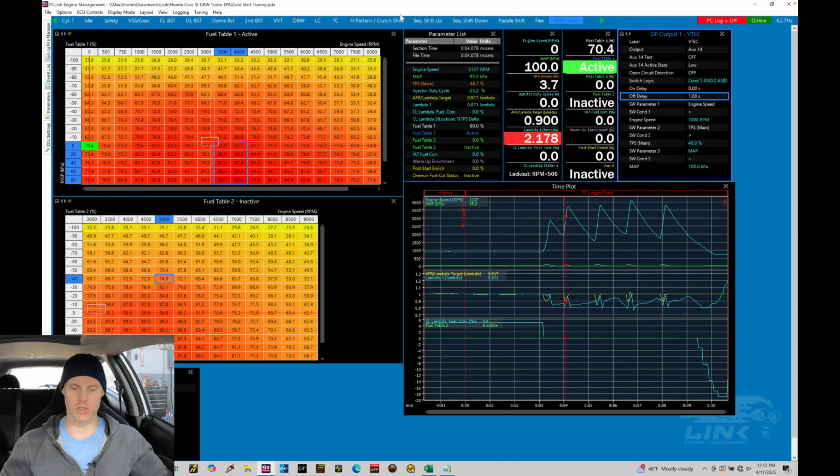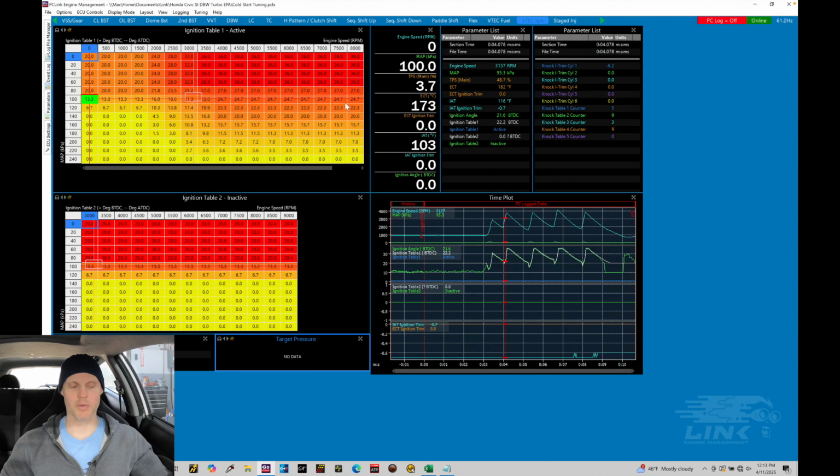Okay, so in addition to looking at our fueling here, so our VE tables, and we have two VE tables, we also have two spark timing tables. So we've optimized our low cam spark timing table, at least in boost, up to about 100, and I think we went up to about 140 kPa. We didn't go any higher. Well, we were creeping higher because we had really low timing in that low cam tutorial when we were mapping things out, and that led to the problem where we were getting an anti-lag type of effect, and we were finding that we were getting a lot of boost overrun.